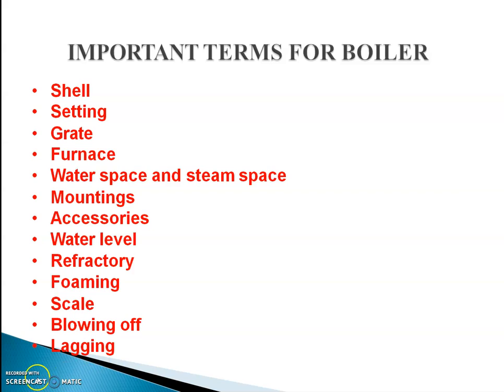Scaling is something we deal with before the water enters the boiler. Through the water treatment process, we have to remove the scaling. Scaling impairs the heat transfer process and also causes medium to extreme hardness deposits occurring on the water heating surface of a boiler because of undesirable conditions of the boiler water.